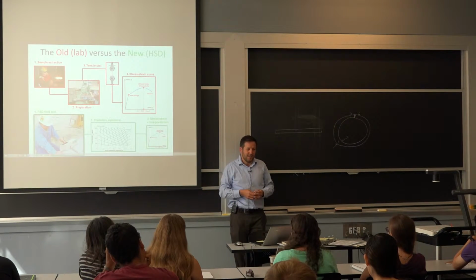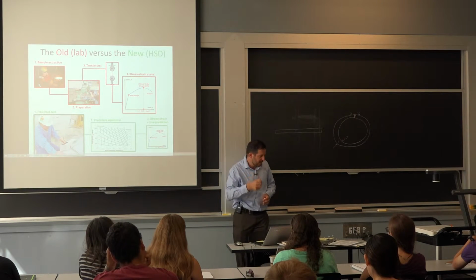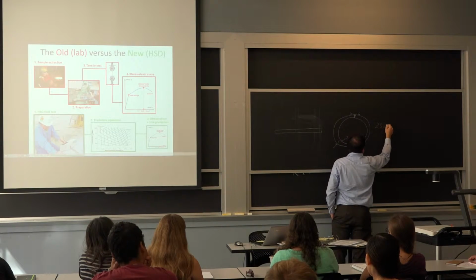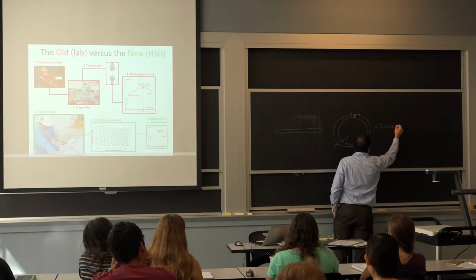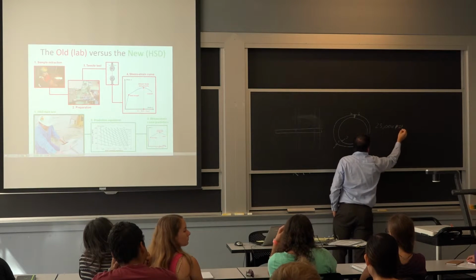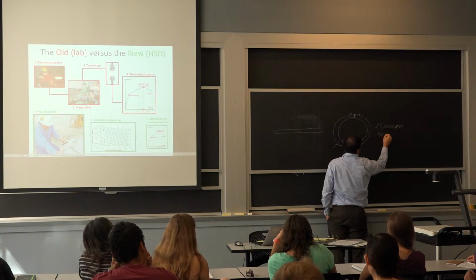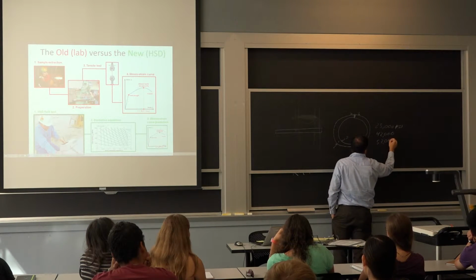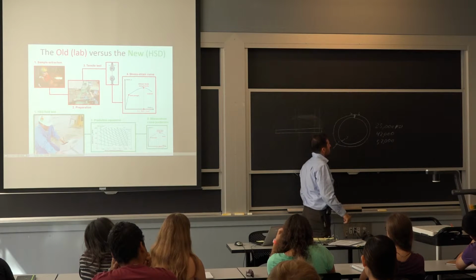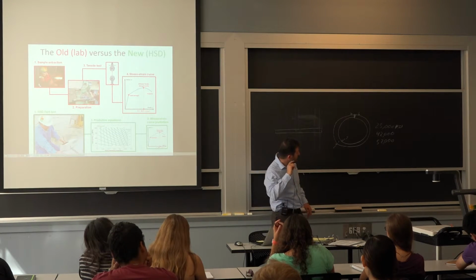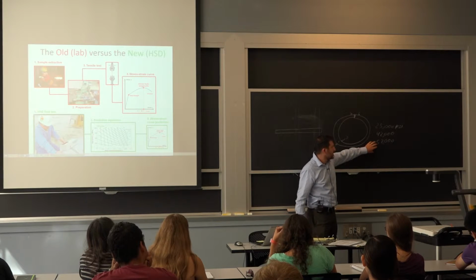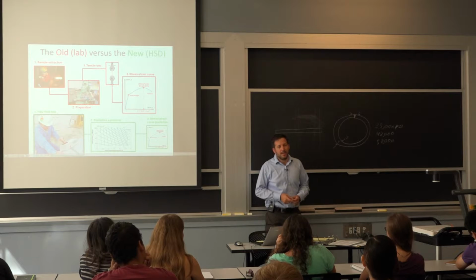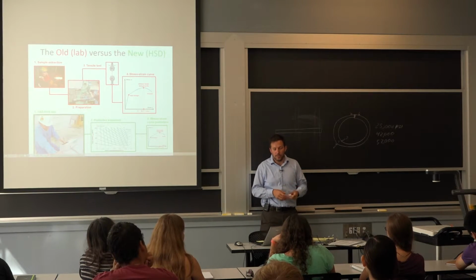And they need to know the standards for strength. You have a 25,000 PSI yield strength. That's the very minimum. Normally, you're hoping to get at least 42,000 if it's good steel, and you have a 52,000. So these are typical grades, or minimum yield strength of the material. And if you don't have a record, maybe you have this quality, but you have to assume this one. So that's a little bit of the background of why we're doing this.